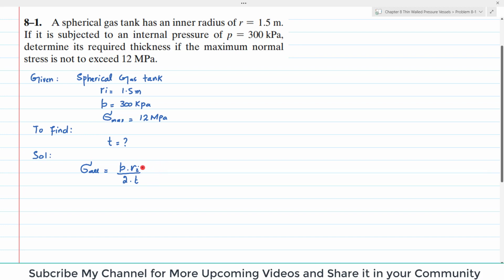Now we have P, the internal pressure, we have the internal radius, we have allowable stress which is maximum 12 megapascal. So from here you can get T is equal to P into Ri divided by 2 into allowable stress.